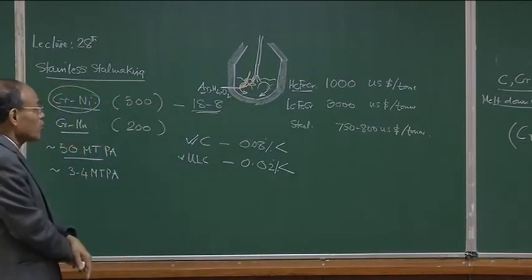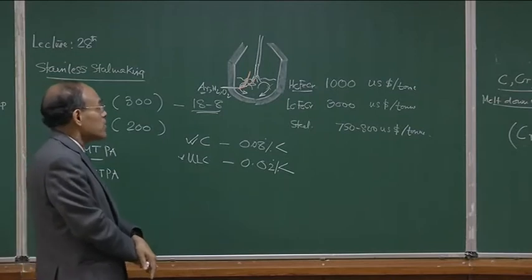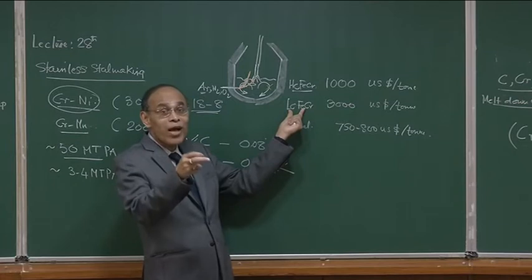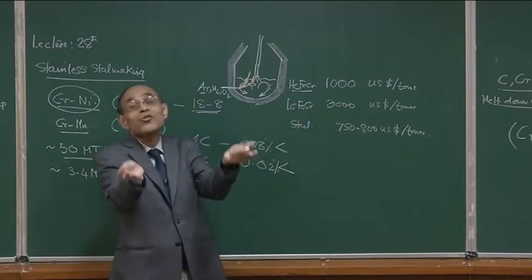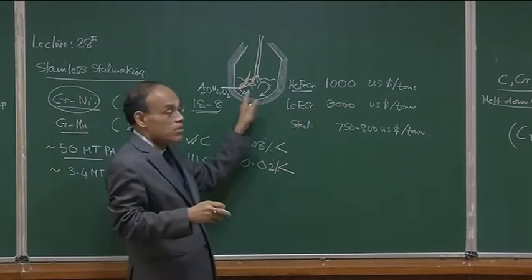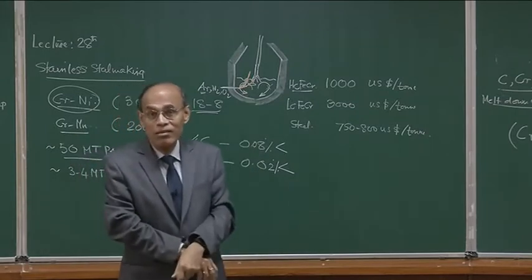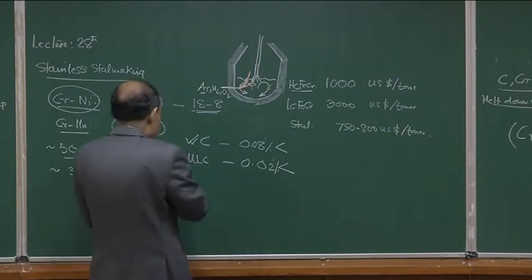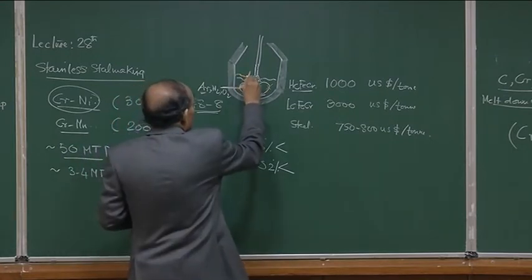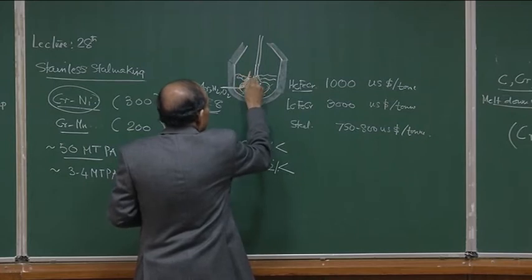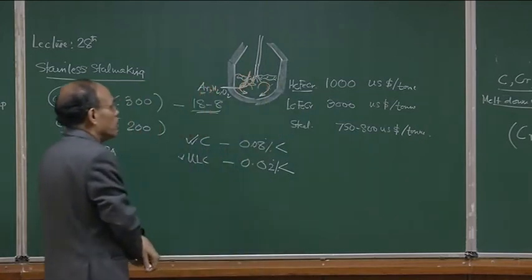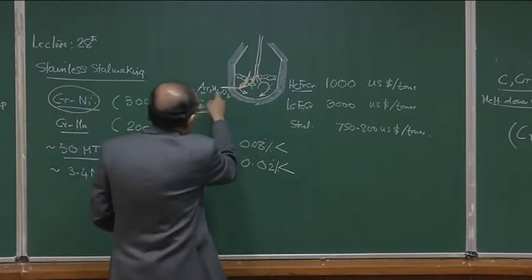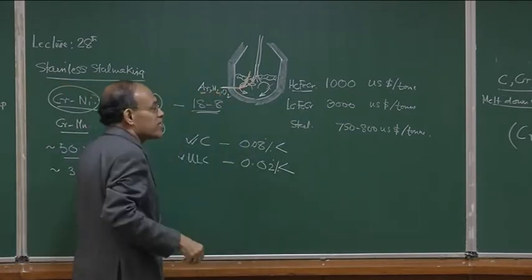At that long time, what happens is you cannot really use low carbon ferrochrome, because then you have to have a lot of carbon. That carbon is going to oxidize, produce heat, and this has to make the process really autogenous. Okay. So, therefore, we have a basic slag which is prepared here, and then you blow oxygen from the top, argon or nitrogen or oxygen from the bottom, and as a result